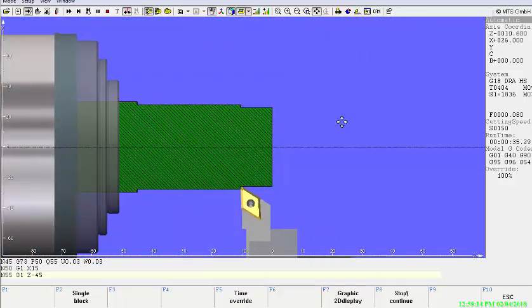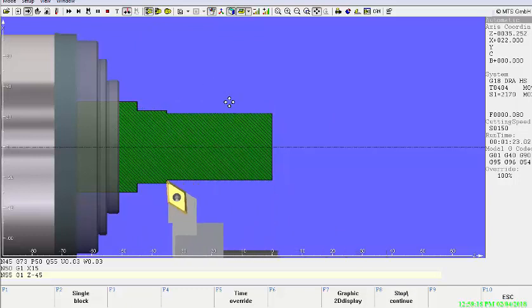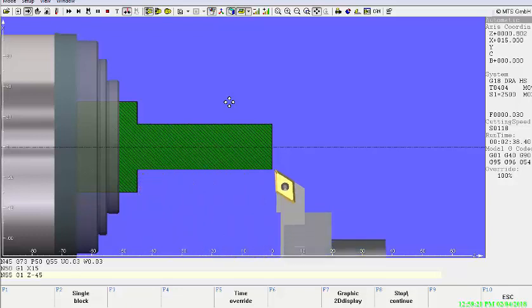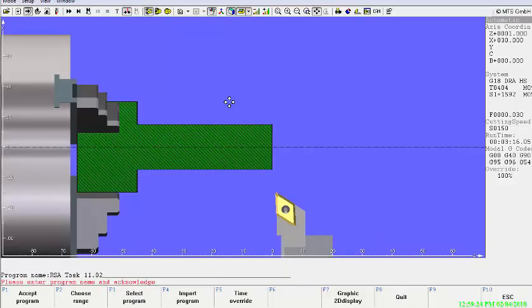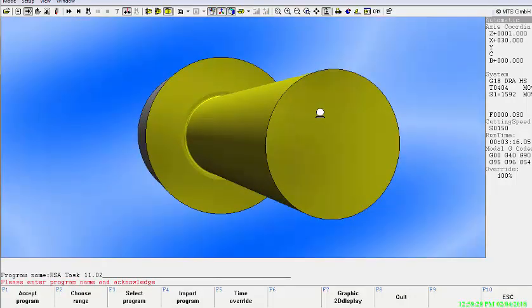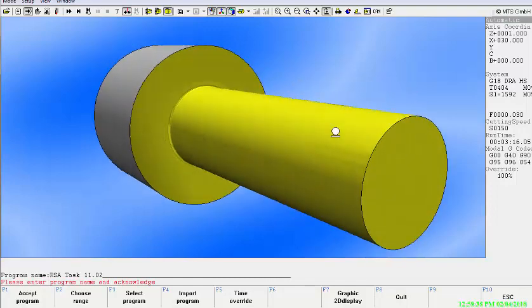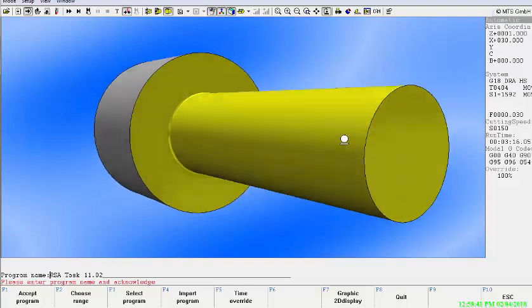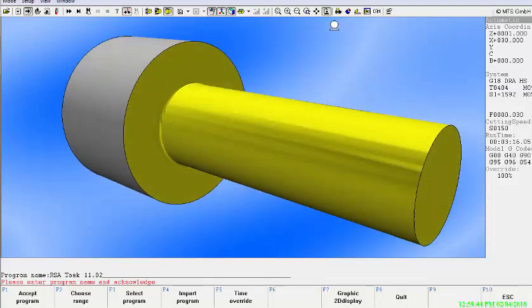Can you see it removed everything? You need to make the surface as smooth as possible in order to prepare it for the drilling operation. This has to be perfectly flat. Without having it flat, it will affect the accuracy of your drilling. I hope that was helpful. You can check it here. Check the dimensions, whether your dimensions are right.